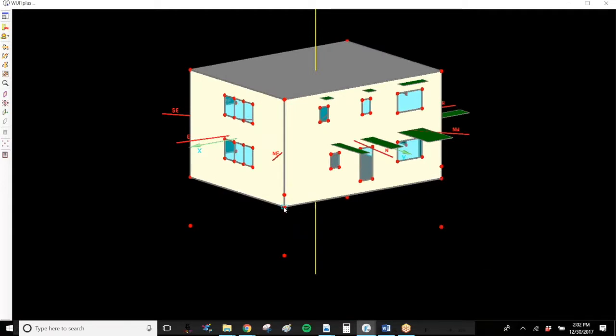So I'll need to do this by selecting the different vertices in a clockwise motion. If you select them in a counterclockwise motion, it will make the wall face one direction versus the other. You can always change the orientation once the wall is created. So if I select them in a clockwise direction, I believe it should make the wall face the correct direction, and if not, we will change the orientation. So I will do this by selecting one vertice, holding Control, and selecting the next in the clockwise direction, then the next vertice, and then the final.